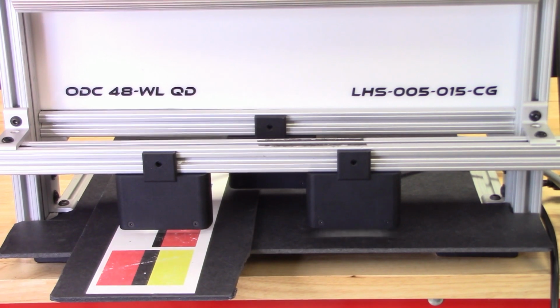For example, if you have a lamination or embossing application where you have multiple layers of web and the web goes through some heating and cooling, different layers of the web may contract or expand, and this might change the width of the web. And if you're just looking at the edge of the web, that may not be representative of the width change that is experienced by a feature on the web. With roll-to-roll, our sensors not only can detect the edge of the web, but they can also detect some contrasting features on the web, and we'll take advantage of that. And with that, we can also look at the width of that contrasting feature.